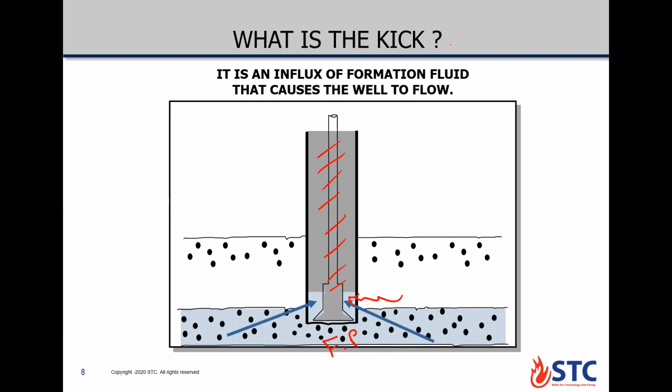So now we have a kick situation. The kick is an influx of formation fluid that causes the well to flow. The formation fluids may be oil, may be gas, also it may be water. Water is also considered a kick, or maybe a mixture of oil and gas. As long as the formation fluid is inside the well, it's called a kick. No migration or movement happened for the influx, so it didn't reach the surface yet.